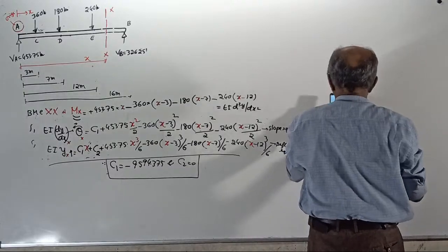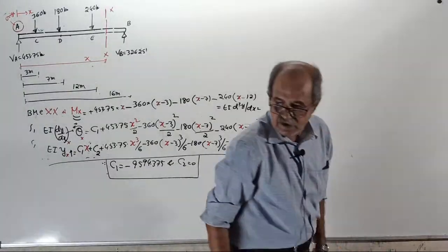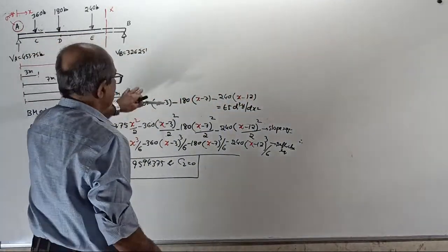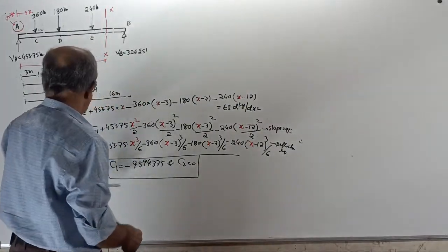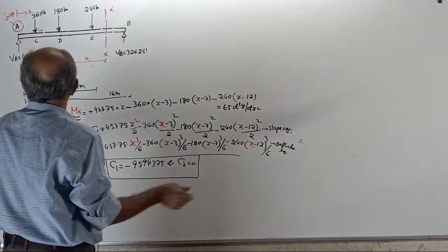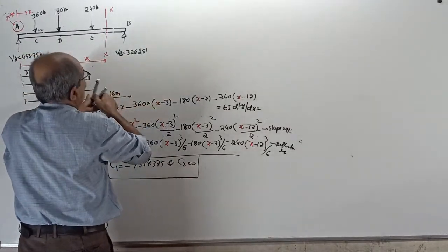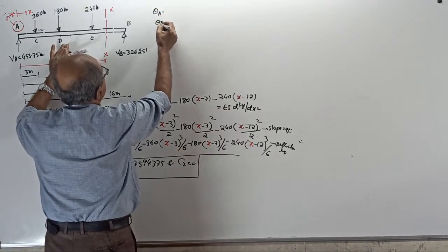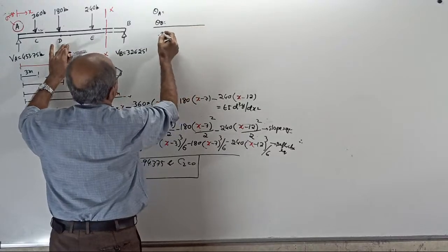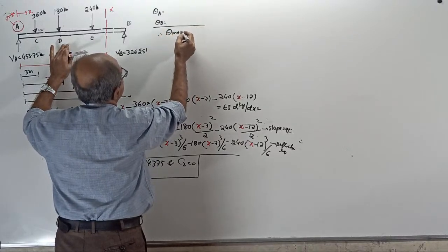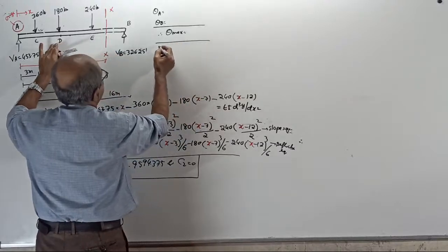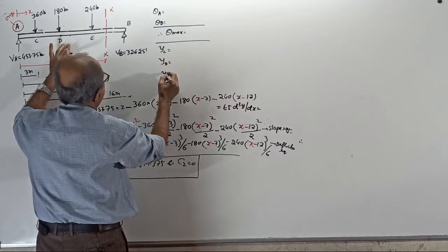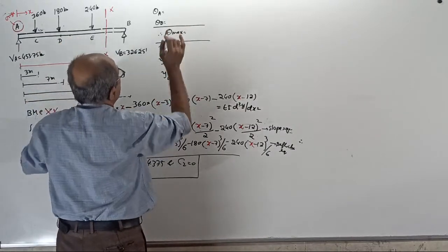Okay, clear. Okay, I'll start. I will not look at the chat box for some time. I'll just tell the principles. For this question, I told you to get theta A, then theta B. Once you get theta A and theta B, you get theta maximum. And then deflection at C, deflection at D, and deflection at E. This all will come in terms of EI.